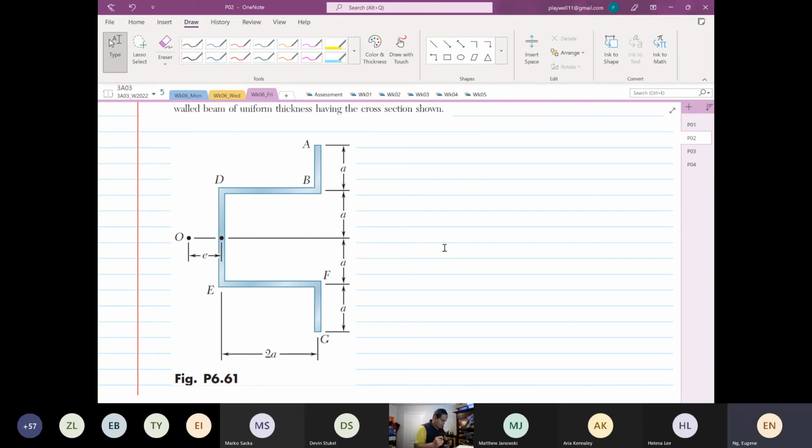If you look at 2a down here, 2a is measured from the center of the vertical member going down here. Can you see when I draw the line where it ends? It is not measured on the edges, it's at the center of the thickness.